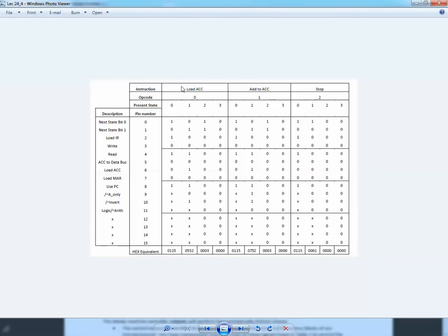Perhaps you won't see instructions that can be processed in more than one micro instruction, or more than one cycle, this semester, but later on in some advanced microprocessor class, you will see these kinds of instructions. So how do we do that? Load ACC will be implemented on a single micro instruction out of the 4, while the remaining we will be actually silent. This is why you expect a lot of zeros here.